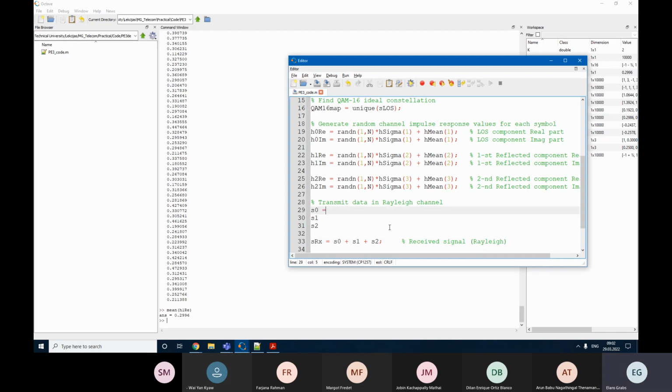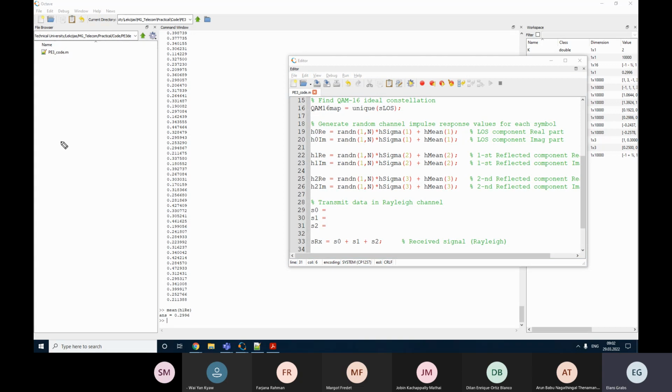So how do we do our filtering? Basically, this is some kind of filtering procedure, but this time we are not going to use the command called filter because each time our coefficients are changing. So instead, we are going to implement this filtering ourselves. If we plot the filter diagram of our channel, it will have 2 delay units. One delay represents travel time, and the second delay the difference of travel time for the second channel. So basically, here we have these coefficients of our impulse response. Now we need to only add up together all these values.